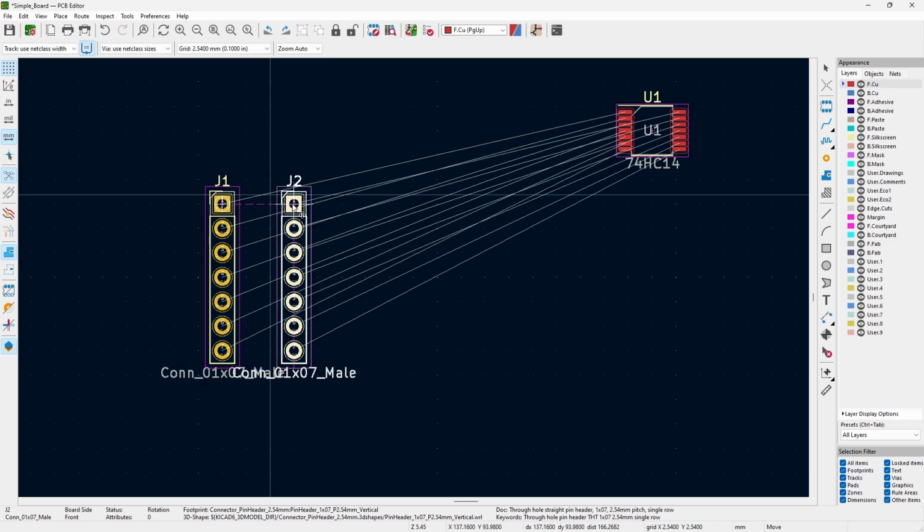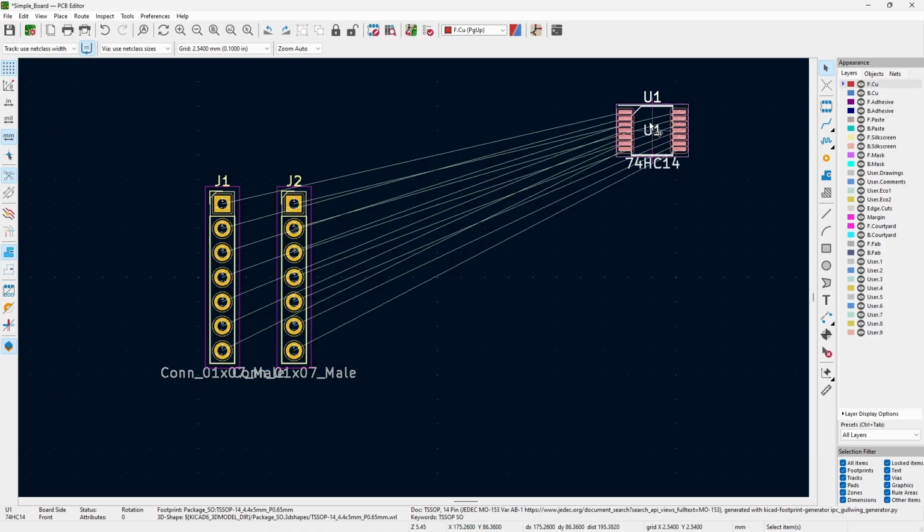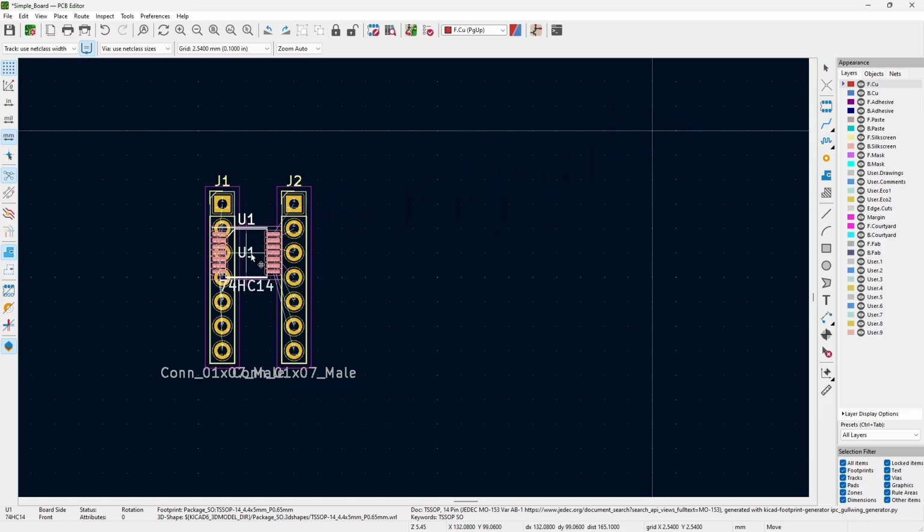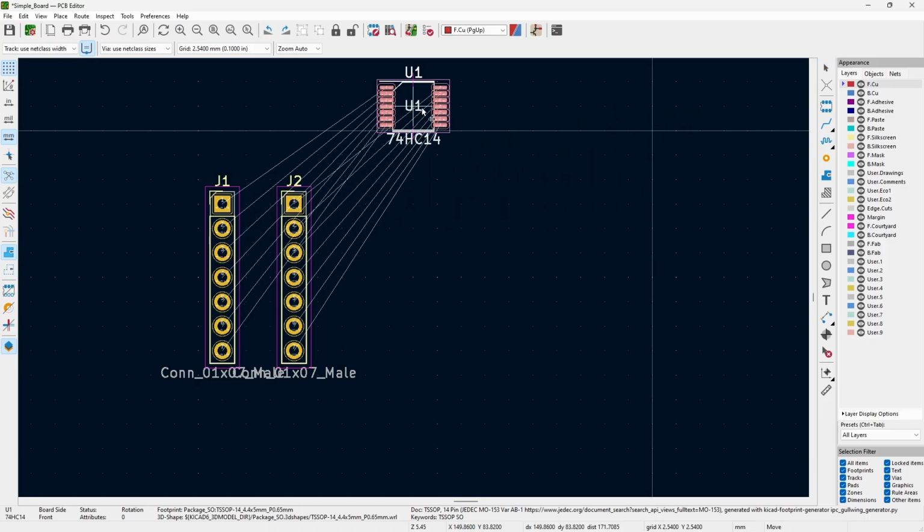So if you want to be able to plug a PDIP device in there and solder it, this is one way to do it. Of course, I'm sure they have PDIP footprints already made so that you could just plug parts into those and solder them. This would work for connecting to a breadboard because they also have 300 mil pitch. But this device up here is not going to fit in between here. I can't put it on there. It's going to interact with that.